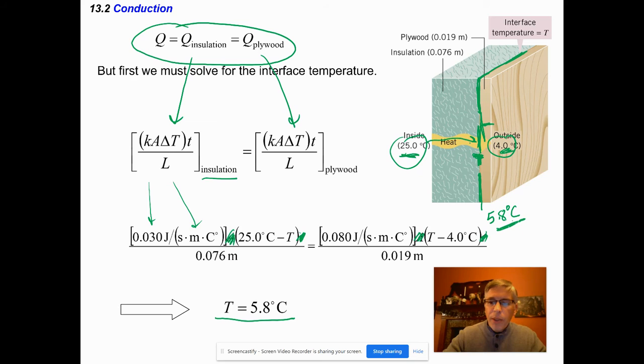Now, key things you'll notice is when you have a higher thermal conductivity, the difference in temperature across there is actually going to be smaller. They actually are inversely related. So a higher thermal conductivity causes a lower change in temperature. The other thing that's affecting it is the length or thickness of it. So it doesn't have much thickness to actually lose that temperature, so to speak. So that's why it's also pretty small. You only have 1.8 degrees Celsius.